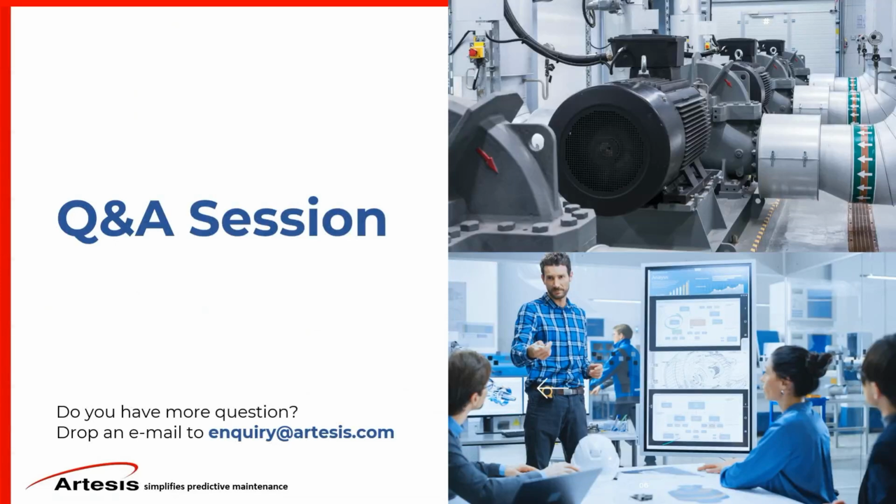Can you test the output of a medium voltage drive? Question from Todd. So we have a motor test tool, if you will. There's AMT Pro, but of course, today we're discussing the MCM. But the answer to your question, if the medium voltage motor has a medium voltage transformer, a PT, and a CT, yes, we can do a test easily by tapping into the secondary side of the transformers there.